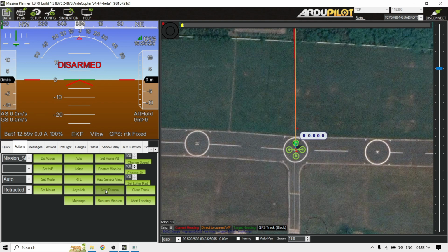So you can't just keep your drone in an armed position for a very long time. Once you arm it, you need to start your mission, or start with the throttle stick. You need to increase it by 5% or 10% and then keep it. Naturally, because of the drone's weight, it will not take off, but it will still be in armed position.